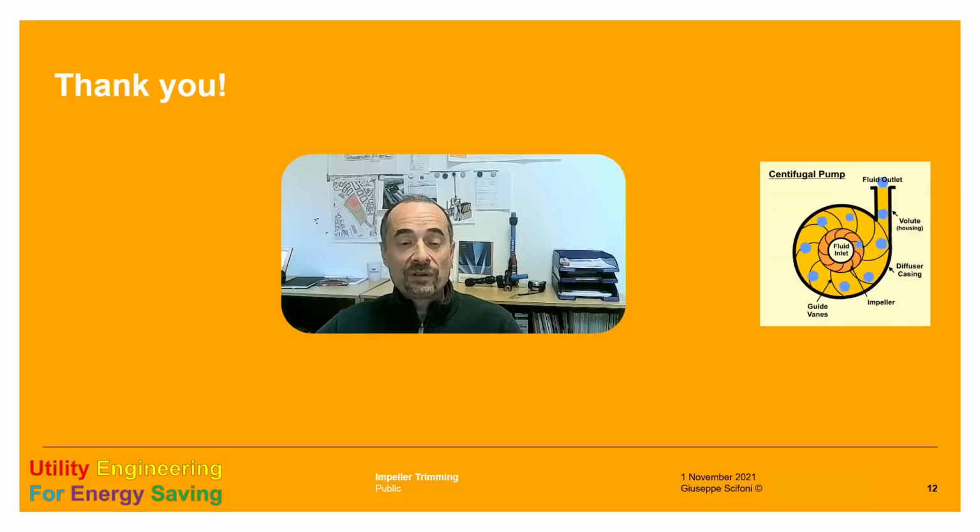In this lecture, we have learned an important concept. In a water circuit, there is no energy saved for free. If we clean an exchanger or increase pipe diameter, that does reduce pressure losses, but does not reduce the power spent by the pump, unless we take a corrective action. And the actions are three: change the pump, use a frequency drive, or trim the impeller. And the last one is the simplest, the quickest, and the most economical. Therefore, we must be aware of that.